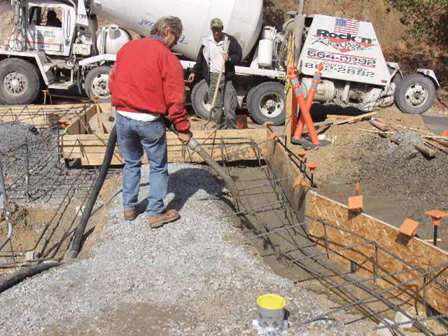On this slab, we went ahead and did the footers first rather than doing it as a monopour, because we did have so many bolts. We wanted to be able to be sure that we could walk around and adjust those bolts to plumb if they were to get knocked out while we were pouring. So this way we can go around, pump the footings full of mud, check our bolts, let it set up, and then come back and work on the slab at a later date.